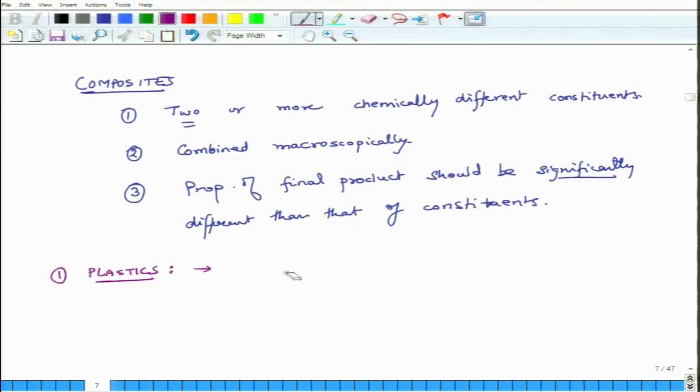If you do the chemical analysis of a piece of plastic from the market, it may have some polymer, it may also have some additives, and for example, one additive could be carbon, to make sure that it has a blackish color. A lot of times they put some carbon in it. And carbon makes the material resistant to sunlight and things like that.